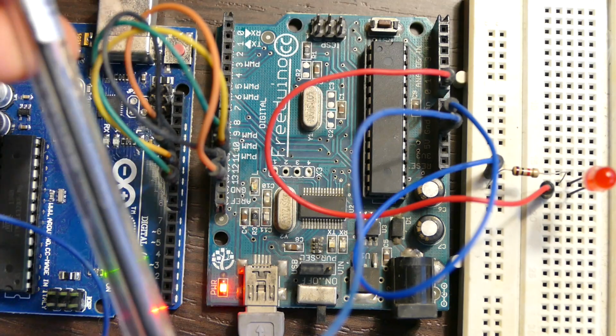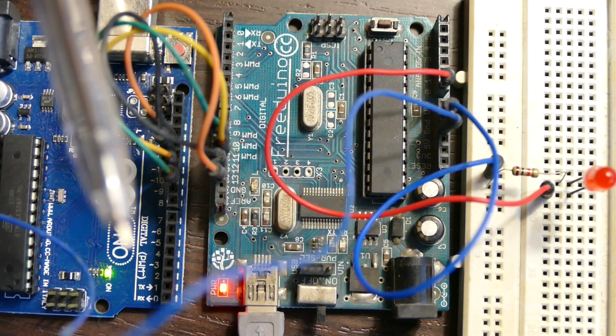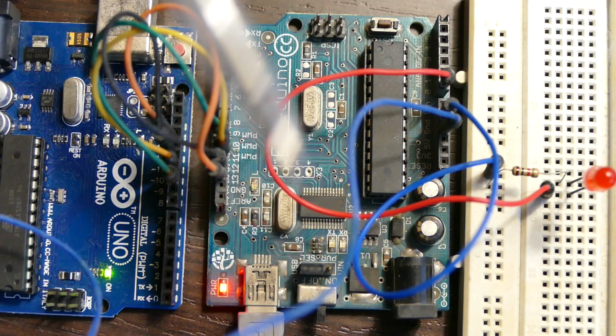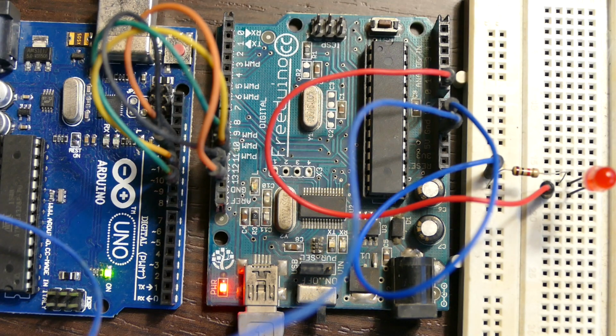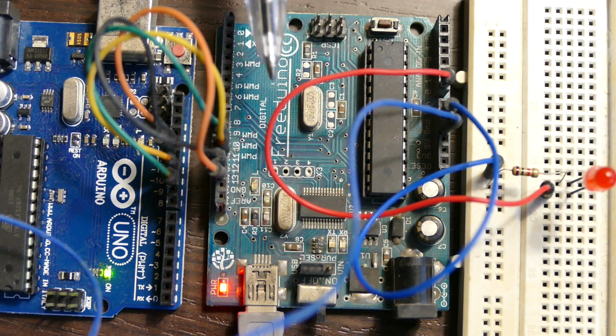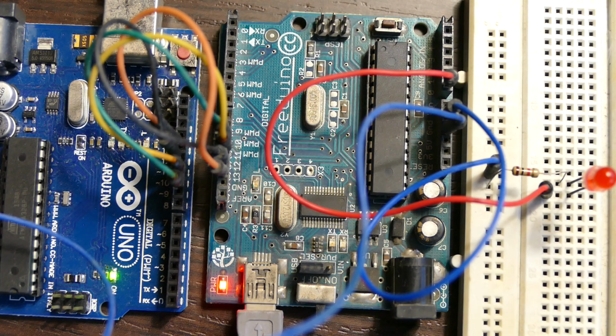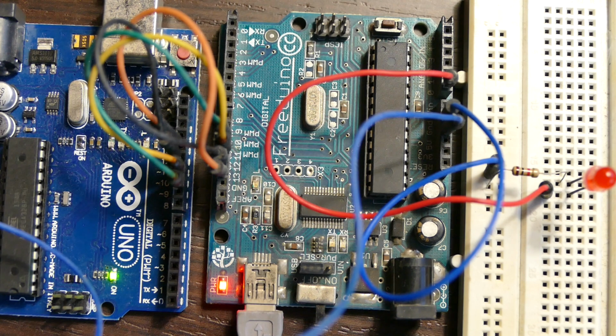And what I also have is, just in case, here's a wire that connects ground from this board to this board. The reason is that these 2 boards are different, so the ground might be different, and hence a logical 0 might be different for this MCU compared to this MCU. If it's the same boards, or if the ground is the same, you don't need this wire. Yeah, and with this setup, let's implement our software.